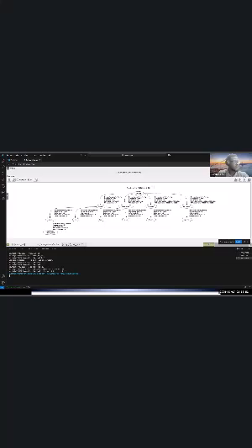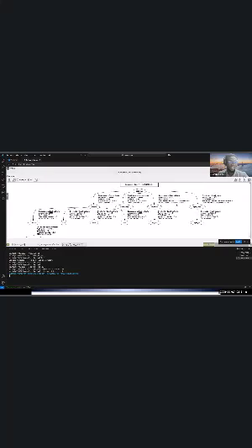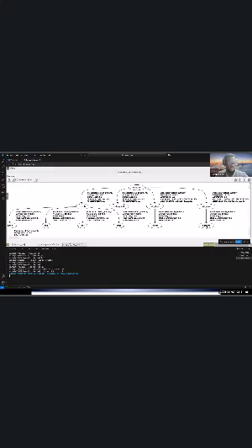All right, so let's close this. Like I said, TF is very important. It's very good so that you can understand transformations, like Devin explained, the different related coding transformation to the base link or to the origin. So base link is like an origin, zero comma zero. When I click on the base link, the chassis, the caster wheel, left wheel, and right wheel are all connected to the base link.